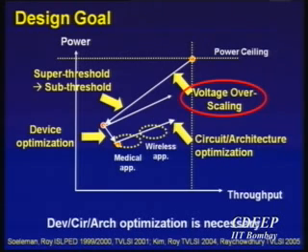So today, I'm going to be focusing on voltage overscaling. What I really mean is that rather than going all the way down to 200 millivolts or so, I'm talking about operating these devices at about 800, 850, 900 millivolts rather than 1 volt. The basic idea is, is it possible that I design it in such a way that I'm able to scale my supply voltage down a little bit? Overscaling of supply voltage, rather than very aggressive voltage scaling, and still do a nominal corner design. That's the idea.